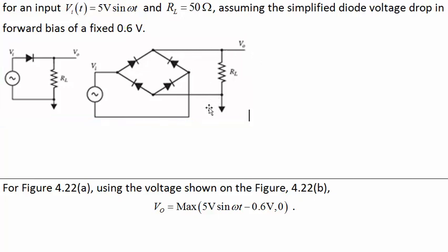So no matter which path we actually took, we go through two diodes. Note that there's no path up through the resistor, by the way. It's kind of why the full wave rectifier is a full wave rectifier. It's a rectifier. It doesn't allow current to go the other direction. It just hits two diodes going in that direction. Going down through the resistor, though, there's one of two options, which go through the voltage supply in opposite directions, depending on what sign it was.